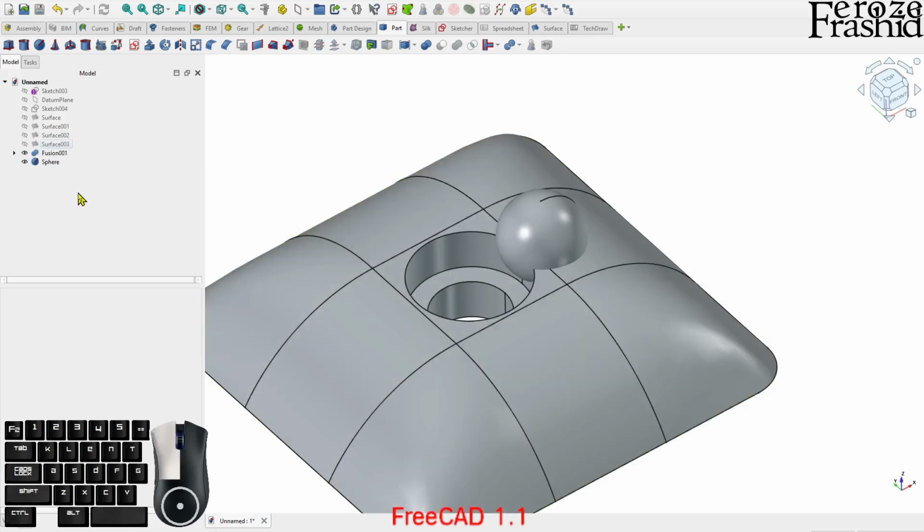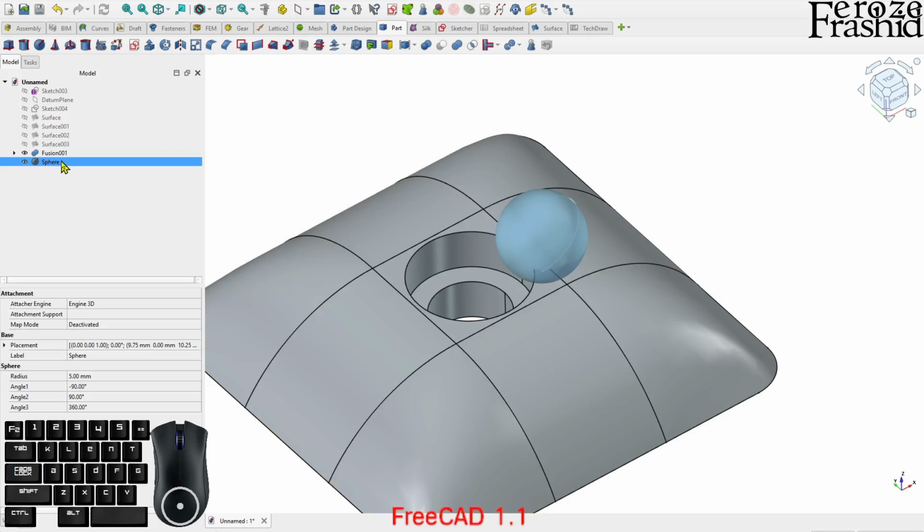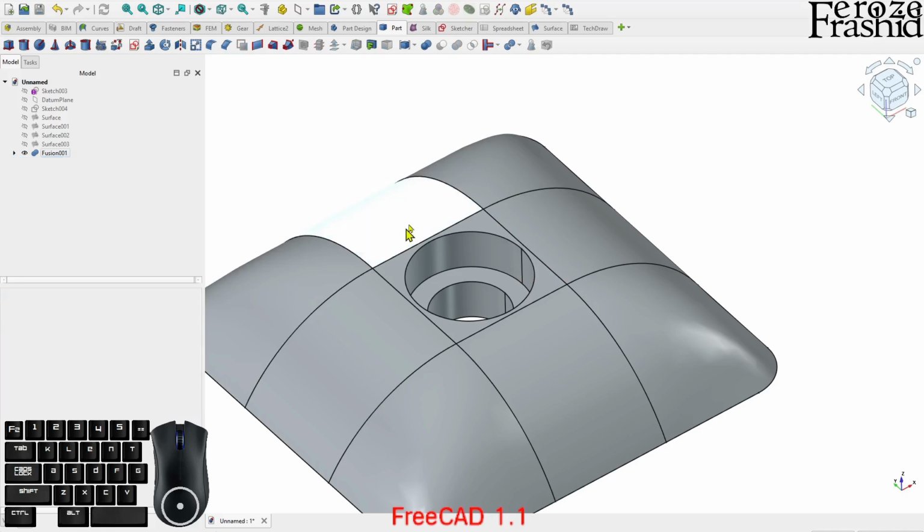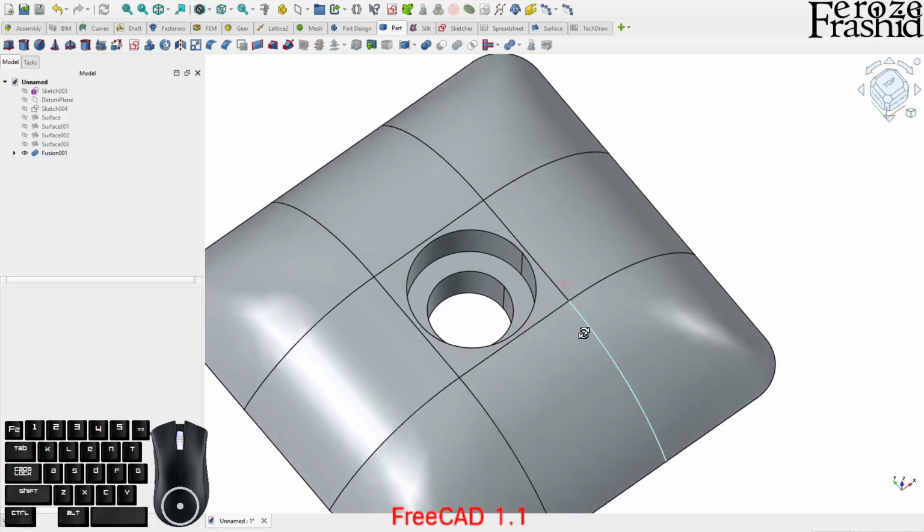But still, always check geometry on your model if you are exporting in a 3D model format. It works 99% of the time. This instance is the 1% where the model is actually working fine, but the boolean operation didn't say so.